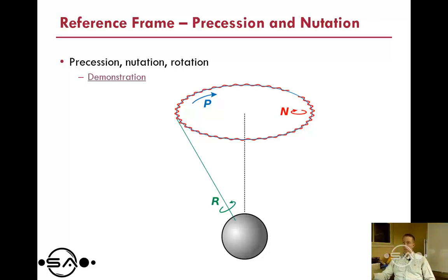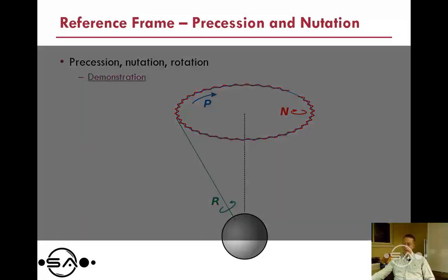So as you guys explore attitude transformation a little bit more and precession and nutation angle, you can actually use these cones. But our precession experiences some variation clearly, and so does our nutation, which causes this wobbly effect as the angular velocity vector precesses or rotates about the original z.